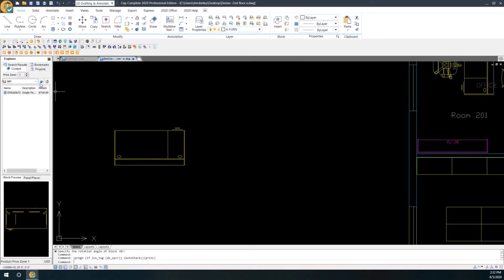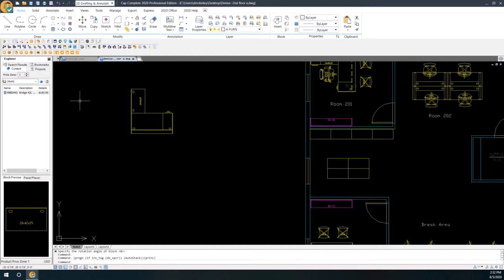Okay. There are standards for every graphic that is made. So there's specific insertion points and there's nodes, making it very easy for you to snap furniture together. So I'm just going to go ahead and do just a quick bridge in this example just to show you. Select it, left click, there's my node, and I snap it and we're good to go. So working with case goods, benching, everything pretty easy. Everything has a node and you simply snap where that node is.